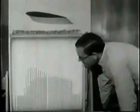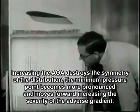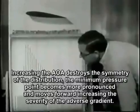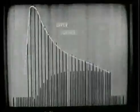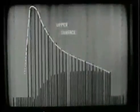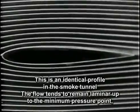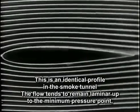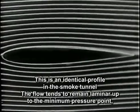Increasing the angle of attack destroys the symmetry of the distribution. The minimum pressure point becomes more pronounced and moves forward, increasing the severity of the adverse gradient. This is an identical profile in the smoke tunnel. The flow tends to remain laminar up to the minimum pressure point.